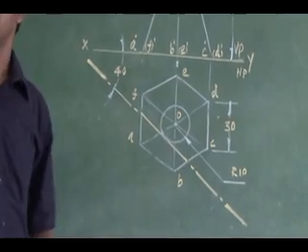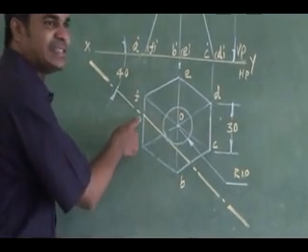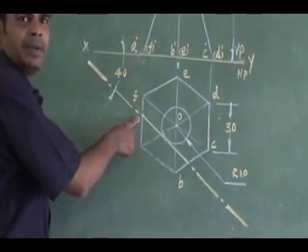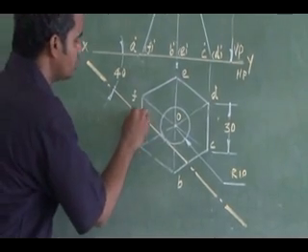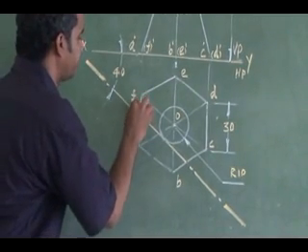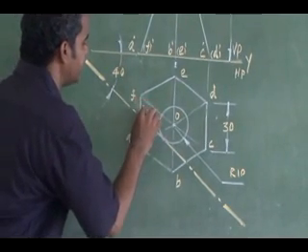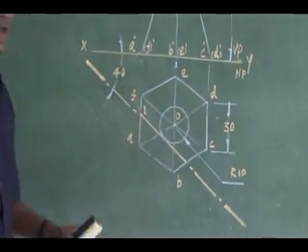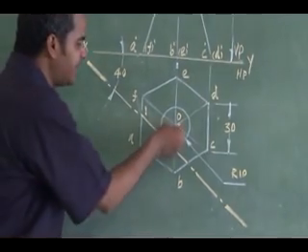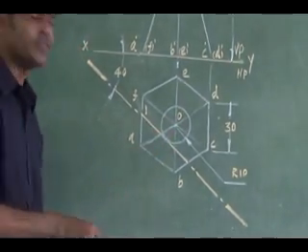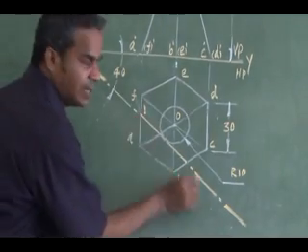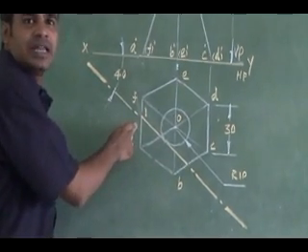See here, it cuts the base here in the extreme. So that is my cutting point 1. Then it cuts the slant edge immediately next. You move along the cutting plane, listen, you move along the cutting plane, searching for the visible cutting edges.